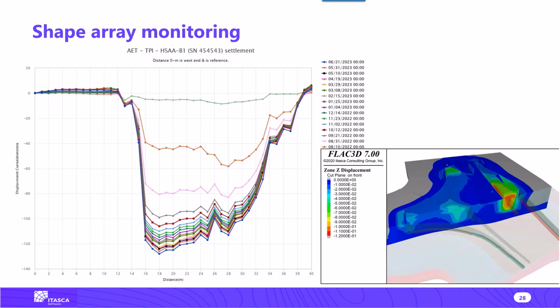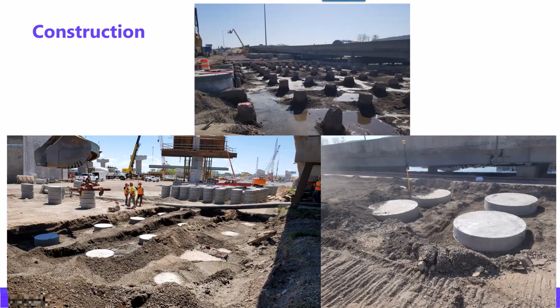So all in all, with this procedure, and I've seen this also in other experiences, in which I go through this CPT calibration process and feed the model, you get a very good, let's say, plus or minus 20%. Obviously, this case was a little bit better than usual, but it gives you a good estimate of the final expected performance.